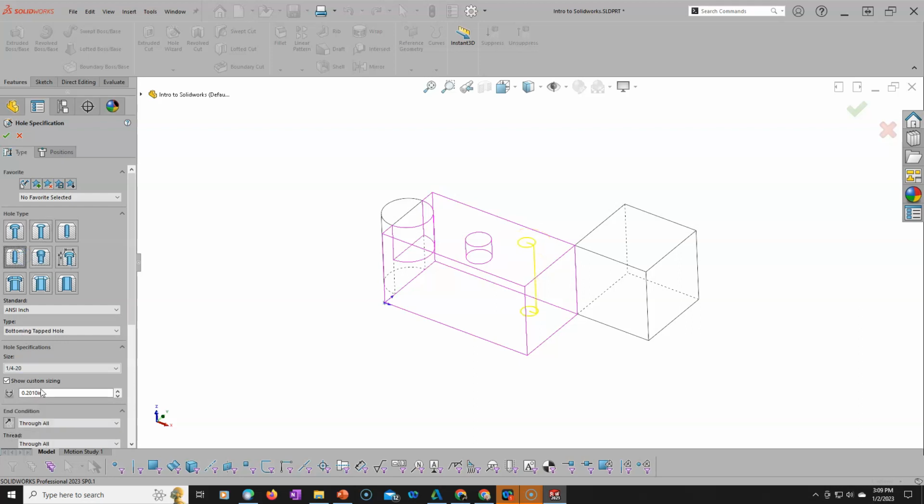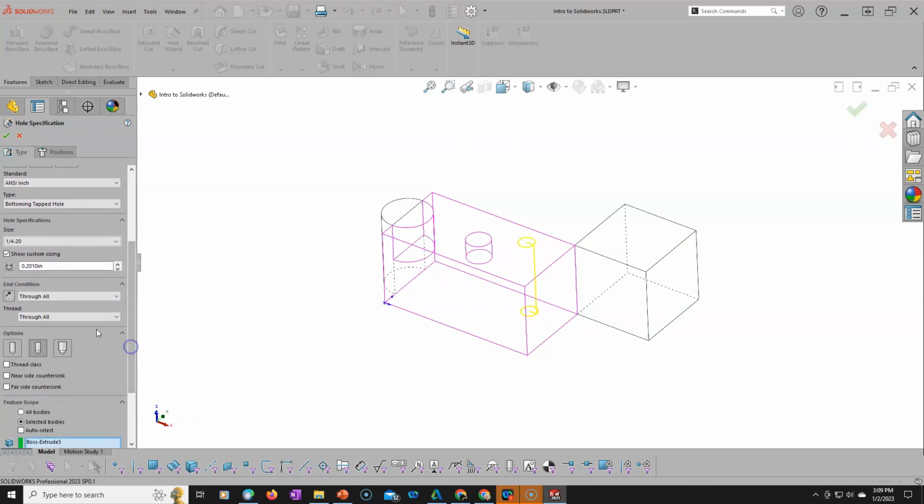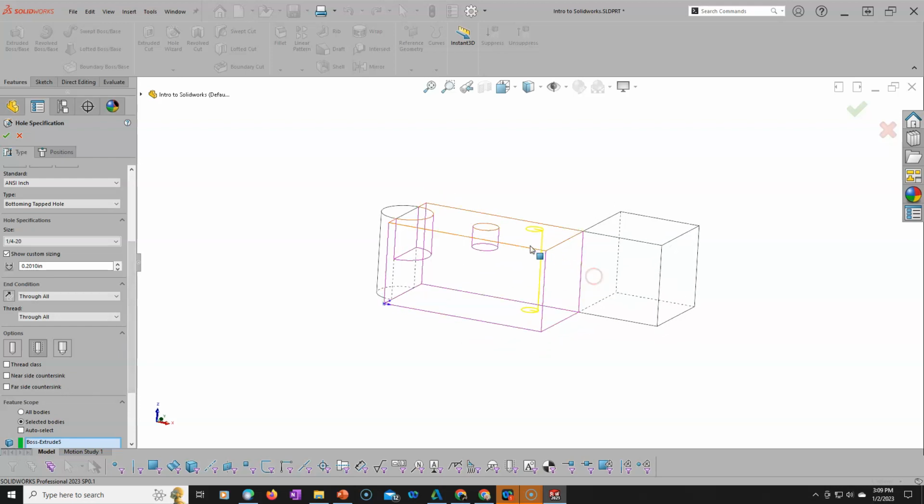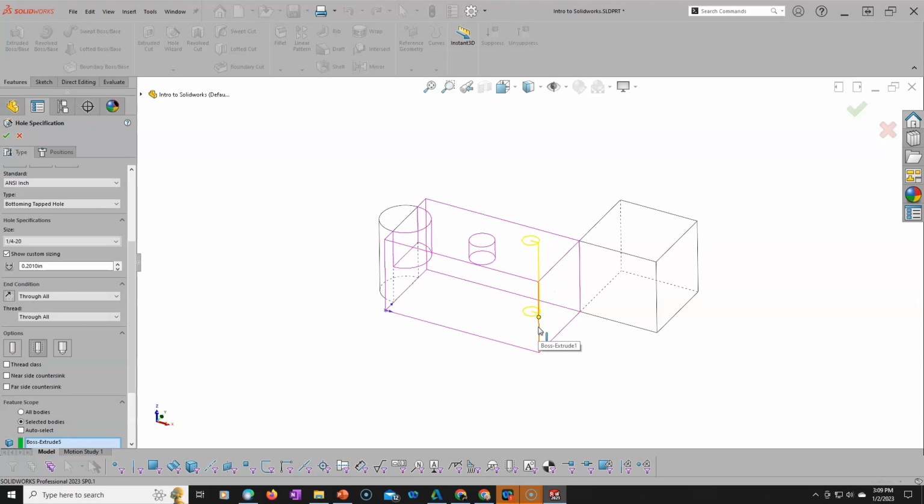The tap tool decides that it wants to be a quarter 20. It shows me the tap drill. We calculated the tap drill for a quarter 20, and there's our 201. Also a through all. The limitation of taps, though, is 1 inch. I may only have an inch of threads to tap with on a standard spiral point tap. If it's not relieved or has other geometry, I may not be able to make it through.